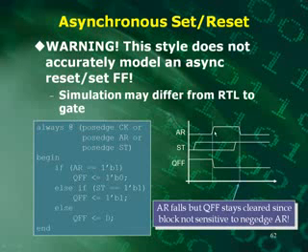Now let's say that while this asynchronous reset is high, an asynchronous set comes along. Let's say it comes along right in here. Now the asynchronous reset, according to this, is going to still keep it low because it has priority. But now we get to this point right here, when we release it, it goes back low, and our asynchronous set is high still.